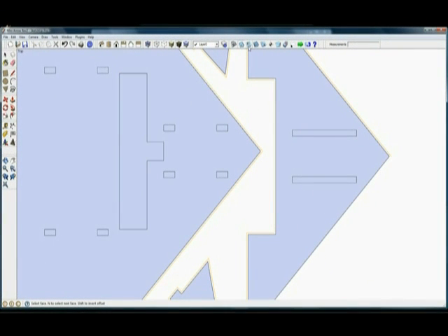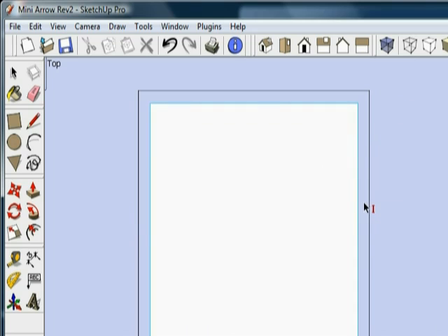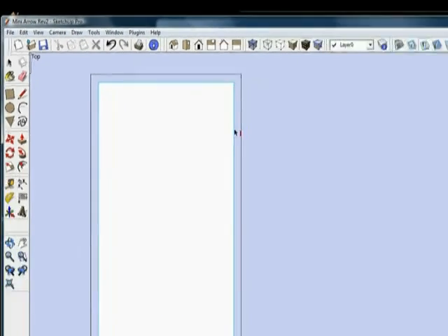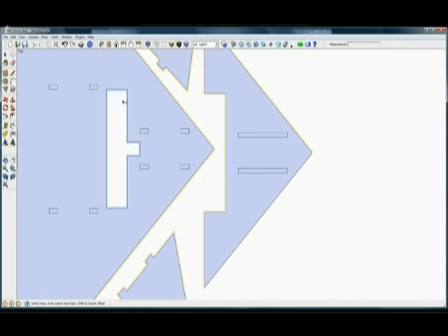So we're going to go over here and get our inside cut tool. I'll click on that. And then now we've got an understanding of a path that's going to be applied to the inside of the part. So if I click now, okay, I've lost the face. That's cool. I haven't actually lost it. It's just not showing up. But now we can see we've got this blue line to tell us that we've got an inside cut going on.